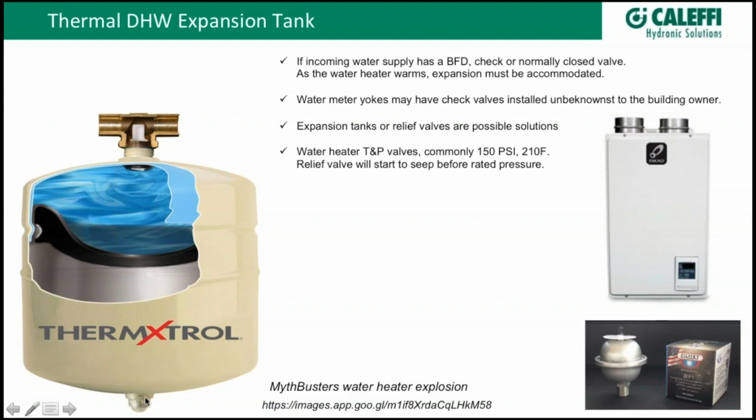Like an expansion tank on a hydronic system, you have to check and adjust the pre-charge. Most of these will come out of the box at 45 PSI, and the reason for 45 is because that's what most regulators are factory preset to. I know ours is, and our competitors all set their pressure reducing valves at 45 PSI, so the tank is pre-charged to that same pressure. Now, if you are going to change the pressure in your system, obviously you want to adjust this pressure accordingly too.